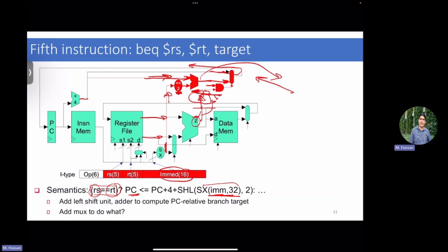Now, if it's a jump, everything here calculates simply. It's not a branch, so you take the first path, you load it here. But this is a jump, so your selection now will be the second one. So you ignore this one, and you go for the second one and load it to your program counter. Is that clear now? So you have 3 cases, but in reality 4. You have the normal program counter plus 4.